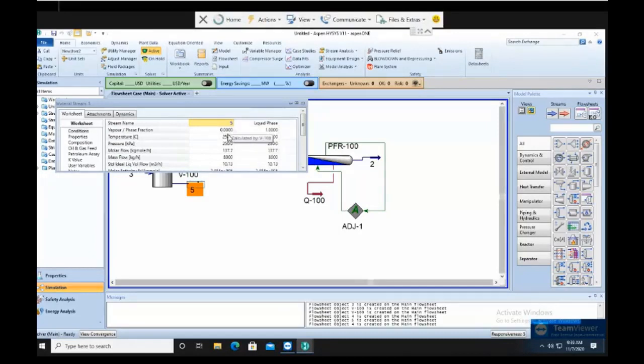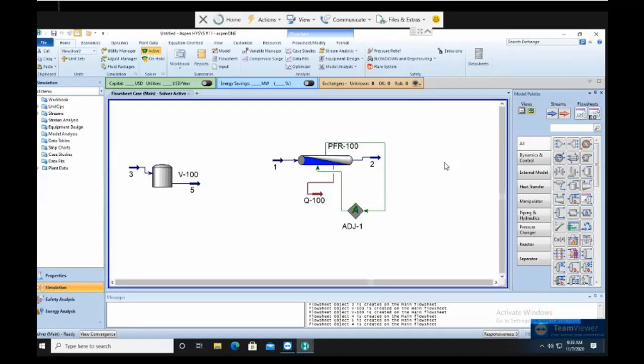Now, we have to vaporize this. How are we going to do it? What is the equipment that we need? Superheater. Boiler. Okay, now. Vaporizer. Yep. Why not? Yeah, vaporizer. But there's no vaporizer in here. So what we have is only a heater. We can put in a heater or we just put a heat exchanger straight away. Okay, let's put a heat exchanger.